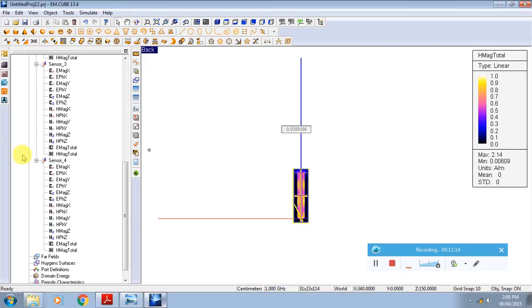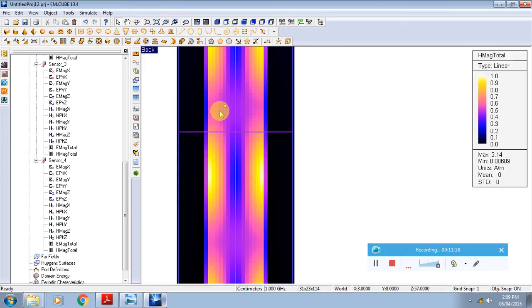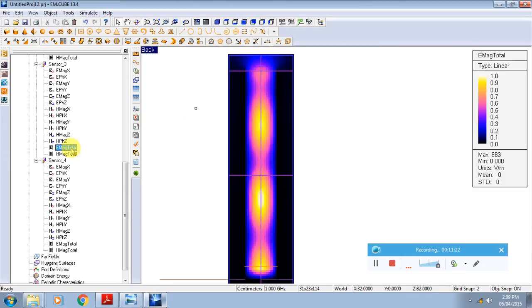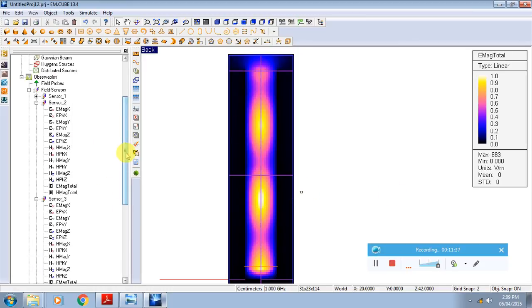Now we are going to observe the triplets. Yes, this is magnetic and this is electric. So these are the patterns which we can also observe in the books. Similar patterns you can observe on the waveguide from the side angles. In this way we are actually varying the TE10 or other modes, exciting the modes and seeing the pattern.